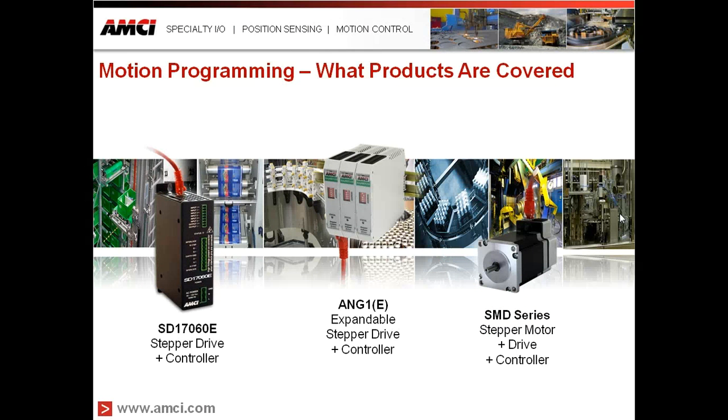SD17060E stepper drive and controller, which is an AC powered stepper drive. We're going to be looking at the ANG1E, which is a DC powered stepper drive controller. And when we're talking about controller and or devices, which are words that can be used interchangeably throughout the discussion, we're also referring to the SMDE and SMDE2 products that communicate to the PLCs. These products are stepper motor drive, control, and motor all in one package.